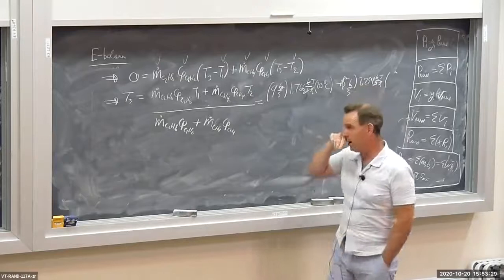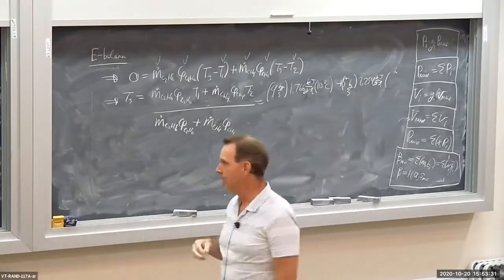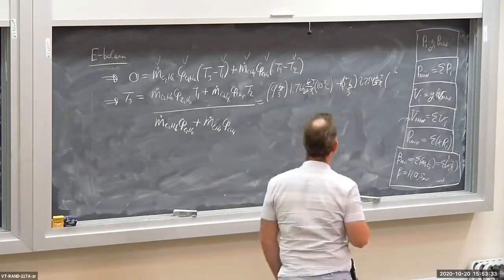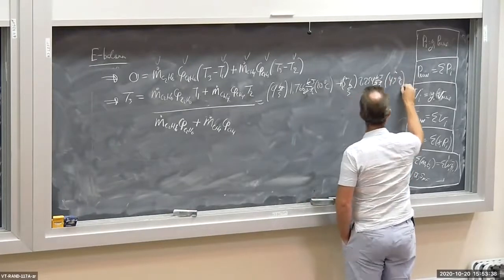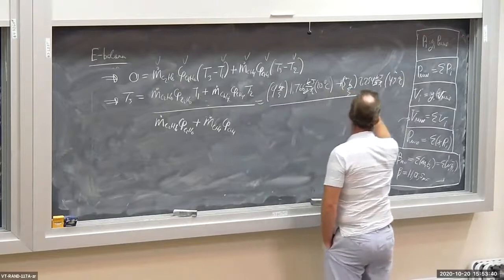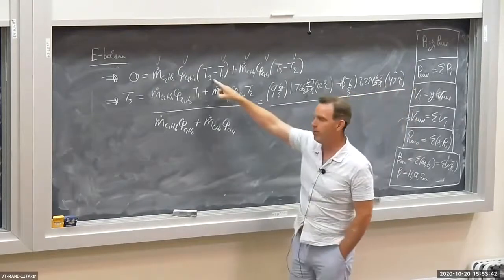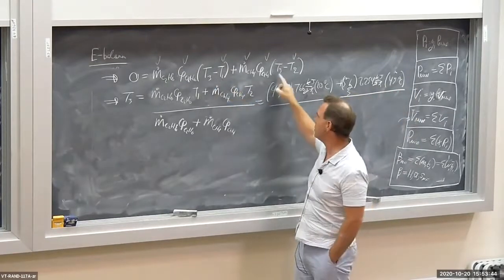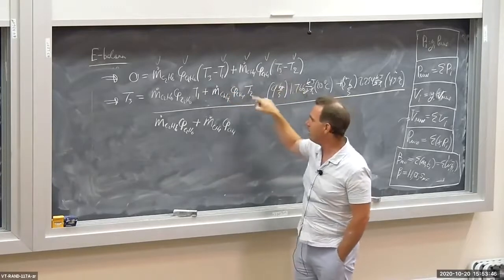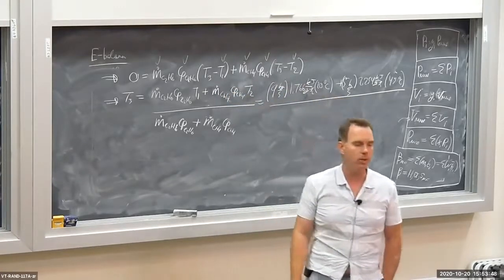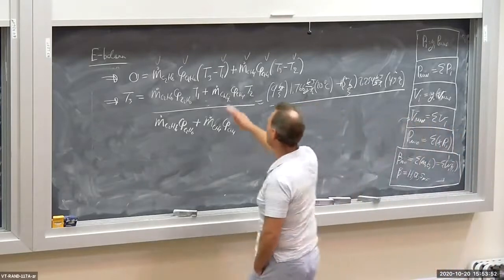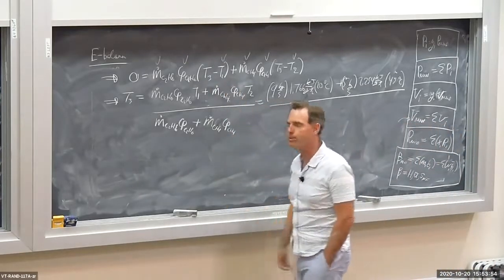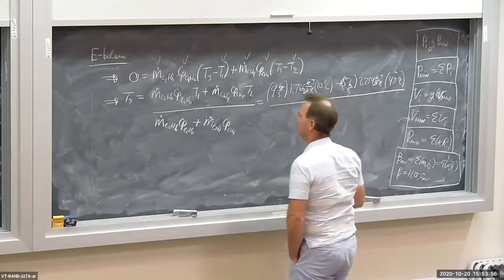And the temperature of the methane coming in is 45 degrees C. Again, it doesn't matter whether I do this in Kelvin or centigrade, because I have a temperature difference here. As long as I write these temperatures all in the same units, it doesn't matter, because the 273 cancels out in the difference here, okay?